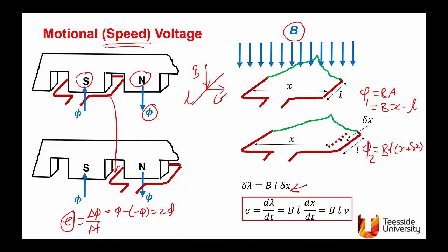If you're studying physics, they will give you flux at a certain angle, and then you will need to find that the normal component will produce EMF, the tangential component is not going to produce EMF. The main thing to note is, in electric machines, we will ensure that B, L, and V are at right angles with respect to each other, and the EMF induced will be given by the product.